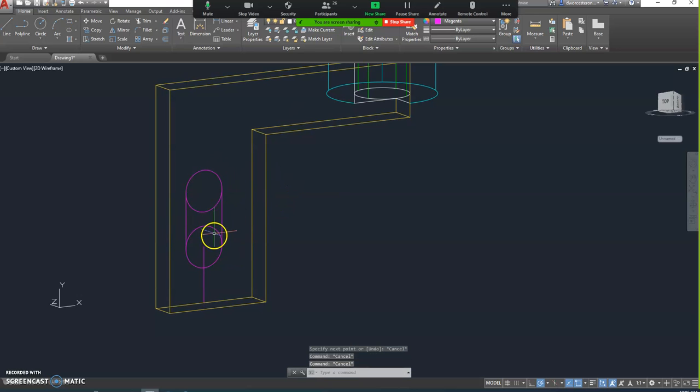This is also a place where having that turn to a wireframe view helps out a lot. It makes it a little bit easier to trim these circles out. So I'm going to go trim and just trim out those 2 lines. And that's looking great right there. I'll pause there for a moment.